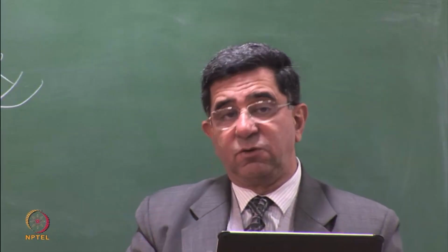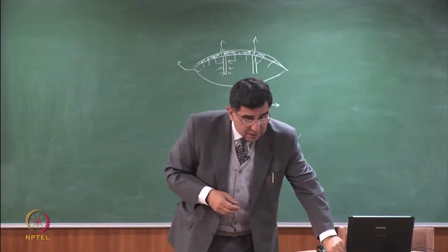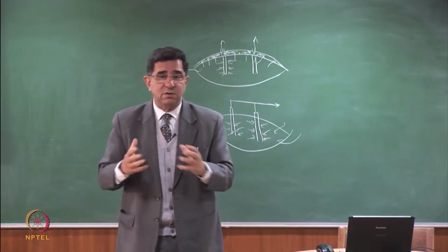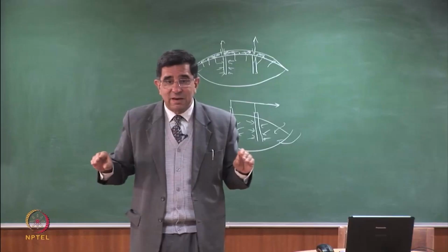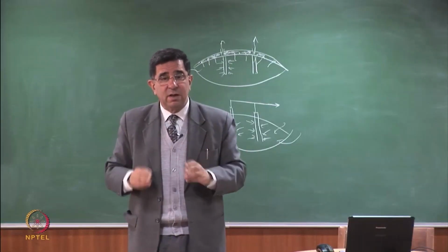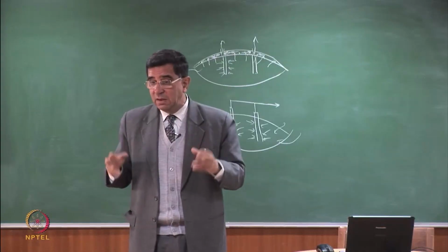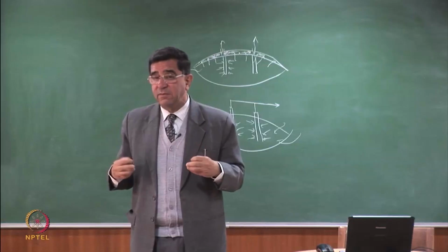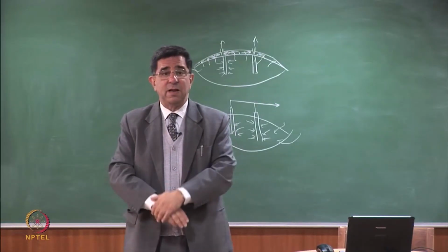So that gives you the overview of gas generation and how we control it. As geotechnical engineers, it's not so much important for us to do the chemistry of what's going on inside, but be sure that the cap is well made, be sure that a gas collection layer doesn't mix with the layers around it. All these preferential paths, the drains, the horizontal drains, the wells, that is all that we have to design so that we can get a lot of gas and we can use it efficiently. So if you have any questions, I'll be happy to answer.